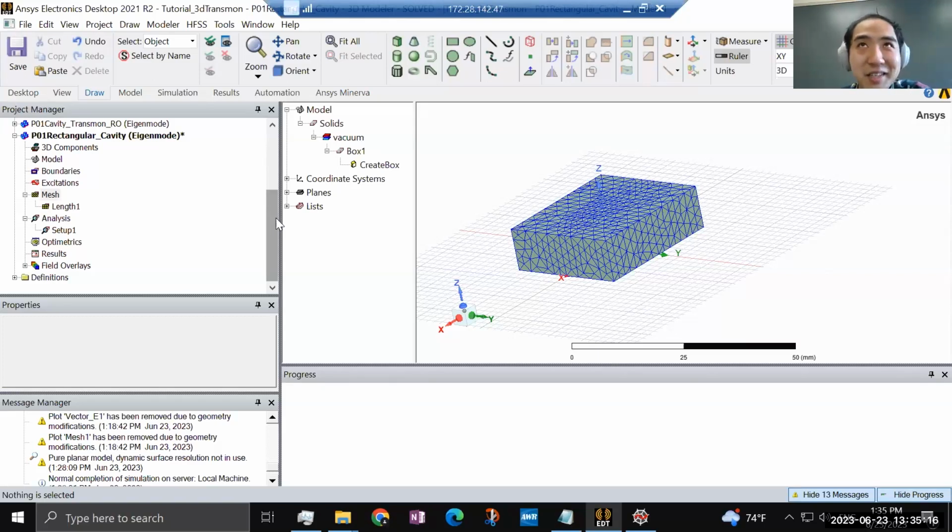Yeah, so I said something wrong just now. I said that perfect E is essentially a superconducting boundary condition, which is not correct, because a superconductor is not only perfect E, but also a perfect Meissner effect, that magnetic field repulsion. So how do I model that?